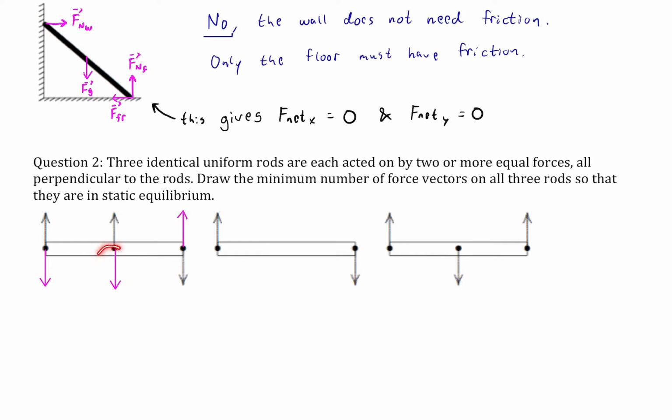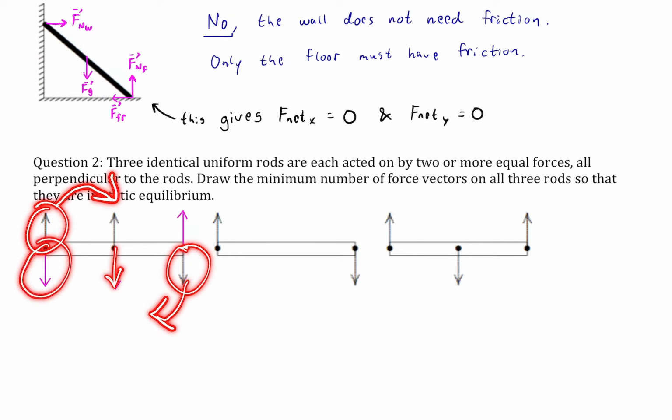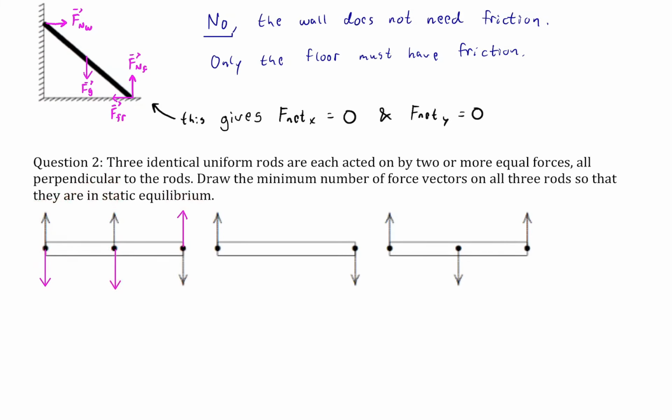All right, so I was being overcautious, because this would be enough for it to not accelerate in the y direction and not have a torque, okay? Because these two here, oh, no, I was right the first time. Because these two forces are actually both agreeing. They're both trying to create a clockwise rotation, see? Both those forces are in agreement, so they don't cancel out, which means we actually do need these two as well in order to cancel out. So we actually need all 3, okay?